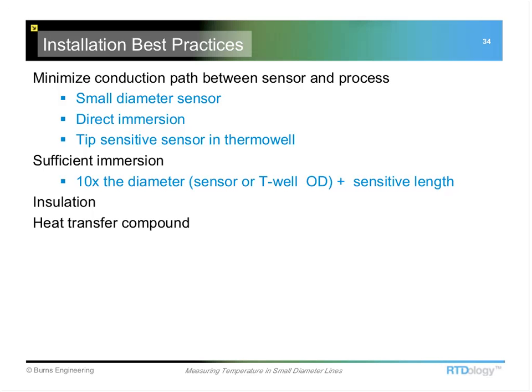And that is with an 1/8 inch diameter sensor, right? You try to go down in the diameter of the sensor as well if you need shorter lengths. Correct. Yep. We do get less stem conduction with smaller diameter sensors, small diameter internal lead wires, just to minimize the path through anything that's thermally conductive.